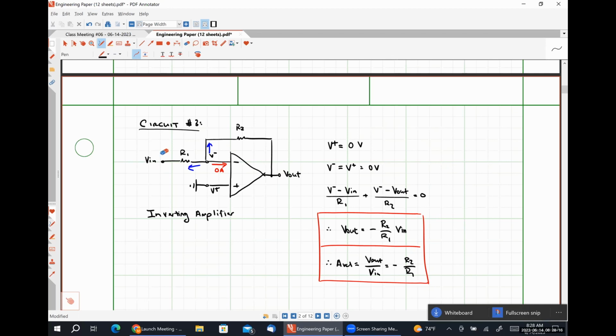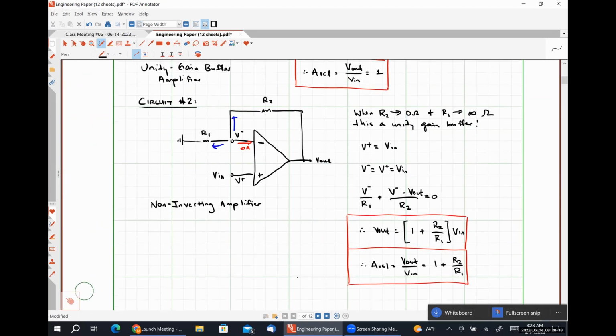If the input signal is applied on the non-inverting side, like we have there, it's a non-inverting amplifier. It's literally that simple. It doesn't particularly matter if we had put some sort of resistor network between where we actually apply this input voltage and this non-inverting input pin. It'll make it a little bit harder to solve for this quantity V+, but the behavior in general will be the same.